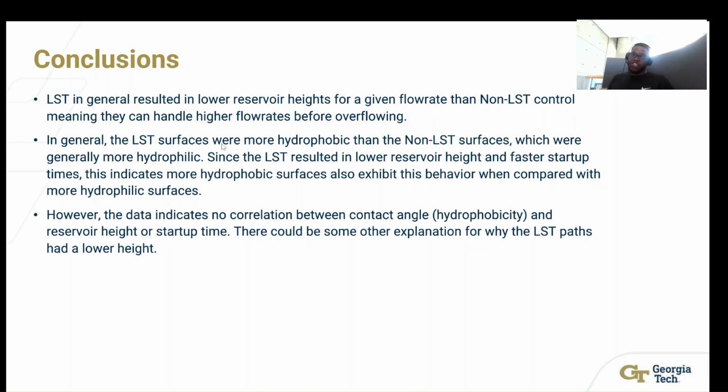We also found that in general, the LST surfaces tended to be more hydrophobic than the non-LST surfaces, which tended to be more hydrophilic. Although we didn't have an indication between the actual hydrophobicity of the samples, which was measured through the contact angle measurements that I mentioned earlier, we still found that the LST surfaces were more hydrophobic, and that hydrophobic surfaces can exhibit lower reservoir height and faster startup time, which is what you want, compared to the hydrophilic surfaces.